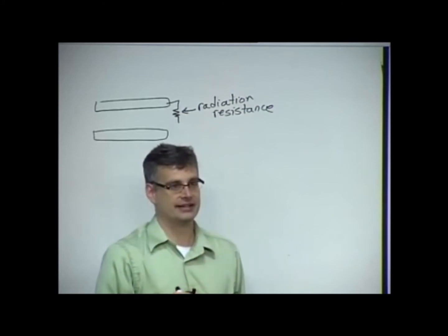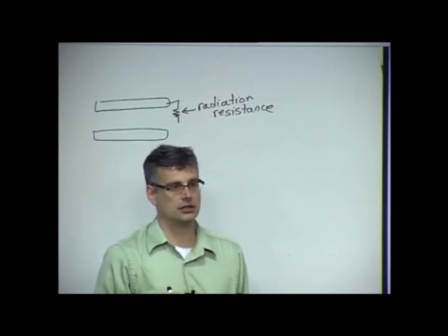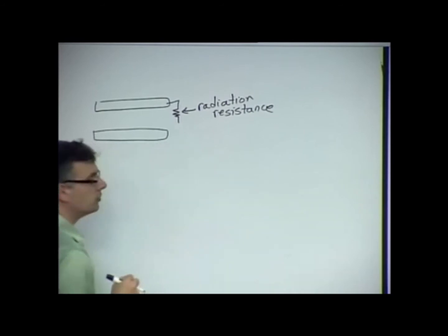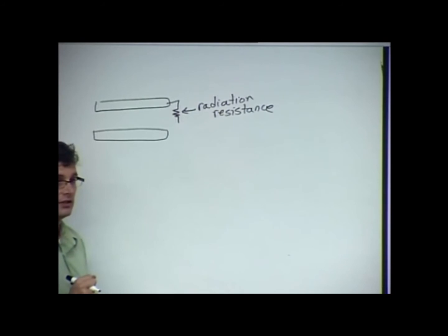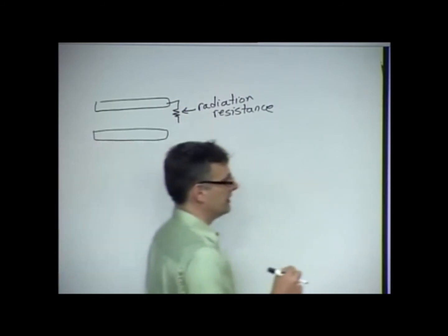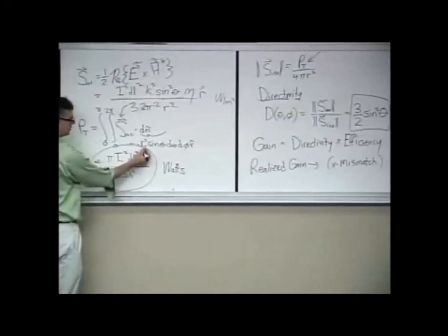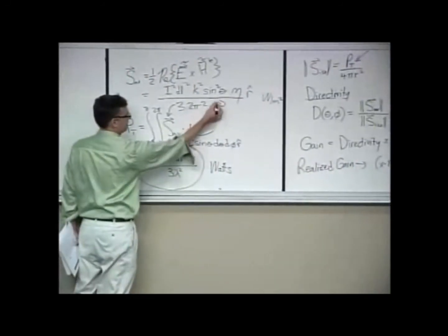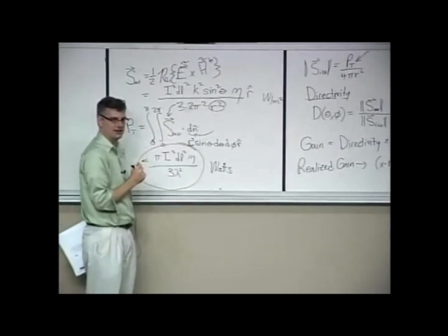Yeah, sorry. It's about the power transmitted formula. So when we integrate the Poynting vector, it's at a fixed radius. Yeah, that's right. So why don't we have the radius in the final equation? Why don't you have an r in the final equation? Oh, so it's at a fixed radius, so I've got an r squared here, but then in here I've got a 1 over r squared, so they always cancel out.